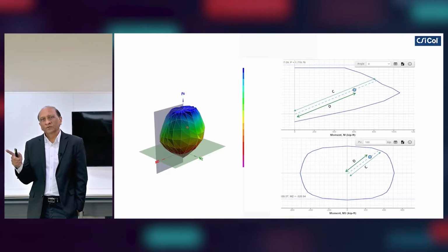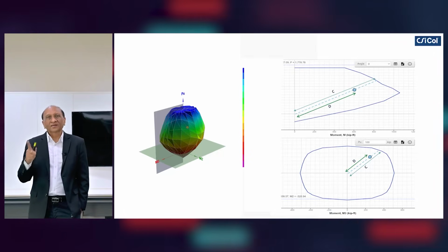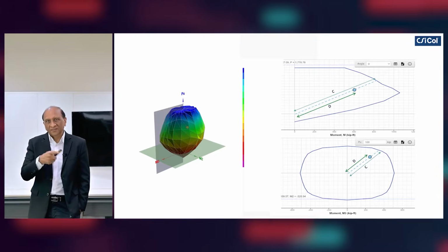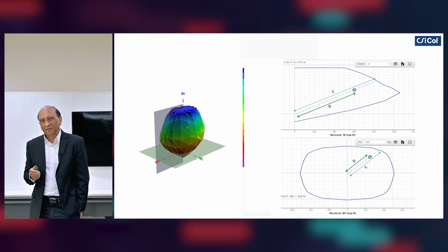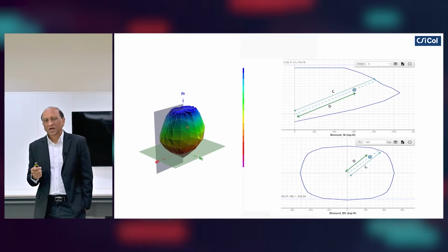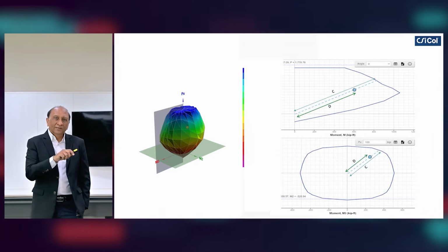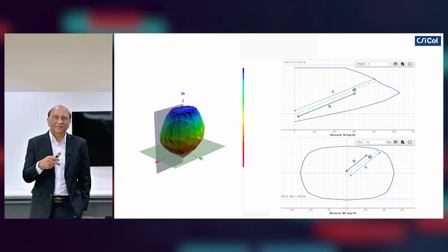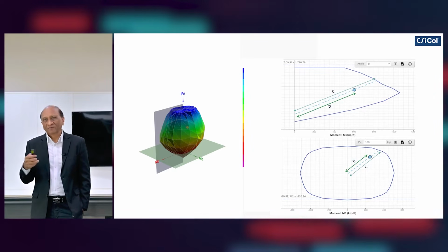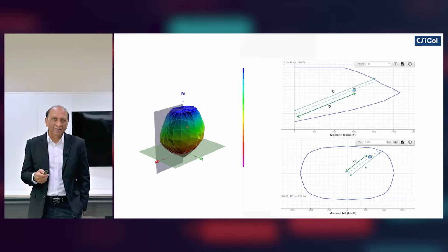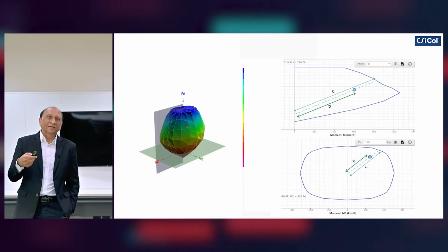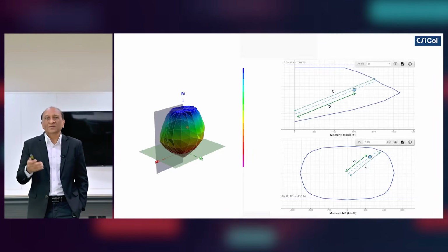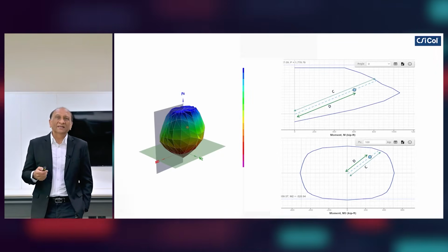Demand capacity ratio for moments may be different from demand capacity ratio for axial load and moment, because their vectors have a different meaning. So now we have two definitions of demand capacity ratio, one DC ratio at a given load level and one DC ratio at a given bending direction. Both may not be the same; in fact, in most cases they will not be. So we can already see that we have a different definition of the capacity. No single number is now clearly valid.